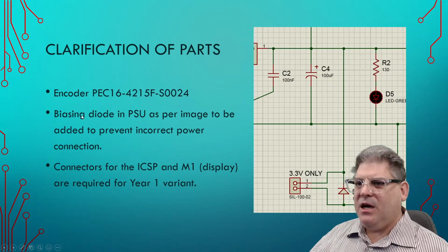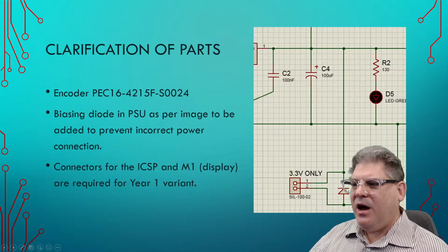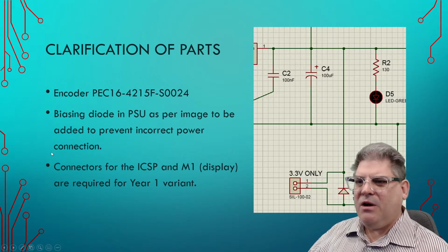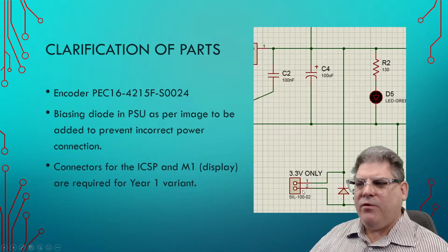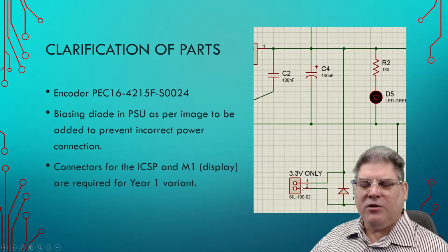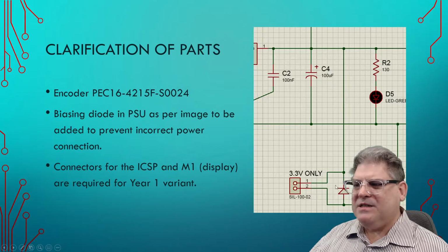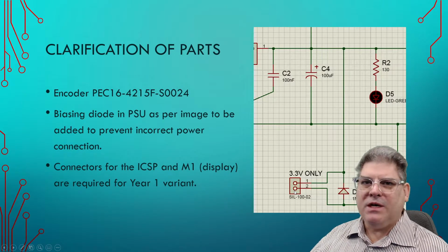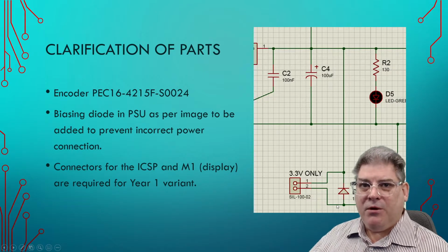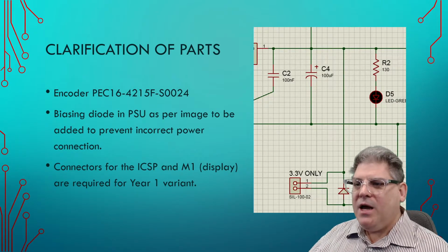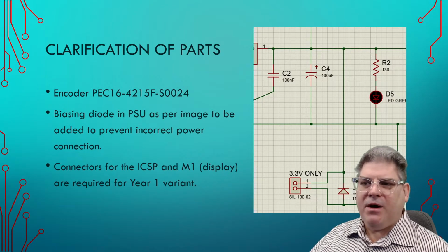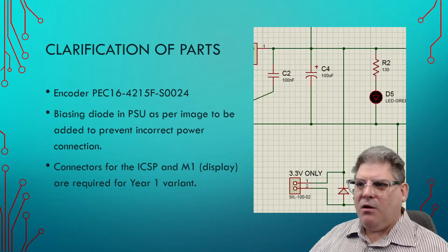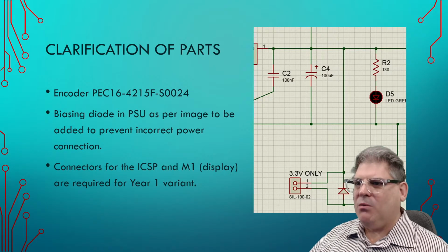That's fantastic. The other thing is that I have a biasing diode. This is not really a biasing diode, it's a protection diode. And so the input for the 3.3 volts, that auxiliary one, what this does is make sure that if you hook it up backwards, it will actually short something out and freeze your power. You should put your power supply into overload. This is a very lazy technique, but it does protect the rest of the circuit, although it may blow a fuse somewhere. That's okay.